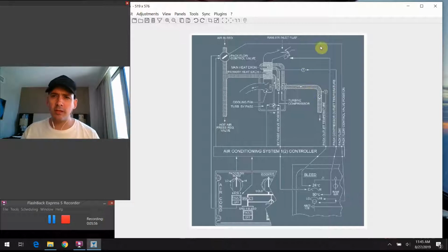And one other interesting thing I wanted to point out, it's depicted in this graphic here: there are these ram air inlet sections on the front of the airplane, and I'm going to pull up a photo of an A320 just to show you what those look like. These actually do differ. We're going to talk further in the discussion about a standalone ram air intake valve that's used for something different. But there are these little forward sections on the belly of the airplane where the air comes in and is allowed to pass over these heat exchangers and extract heat off the hot section of the air passing through all these pipes here, and then it gets blown out the underside of the belly.